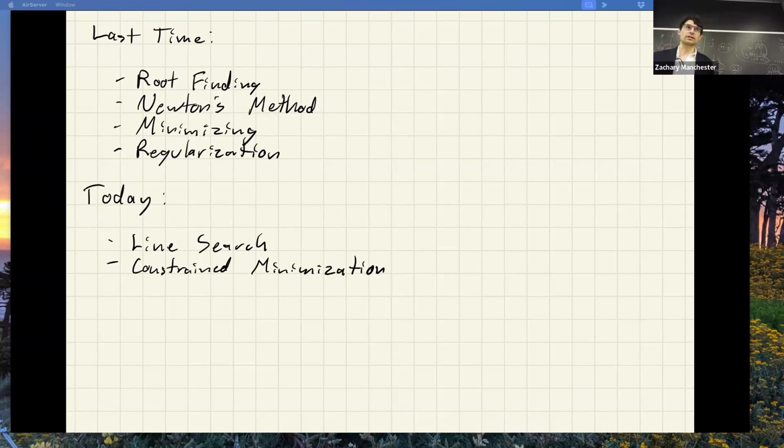Then we're going to talk about inequality constraints, and where those show up for us are like two major things. One are actuator limits, like torque limits. You need to stay within your actuator limits, and the other big one are things like obstacles, safety constraints. So you have control constraints, right? U has to be, say, less than or equal to some U max for your actuators, and then you have like don't hit the walls or slam into the other car. State constraints, those are inequalities, right? Okay, so any question about any of that stuff?